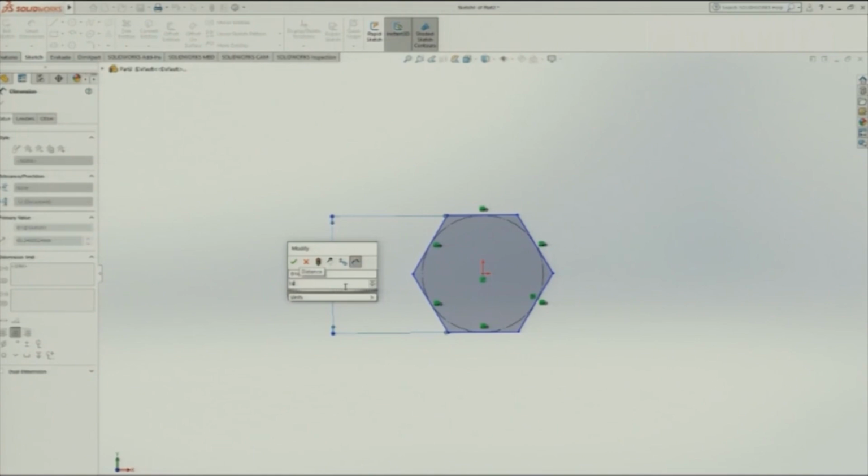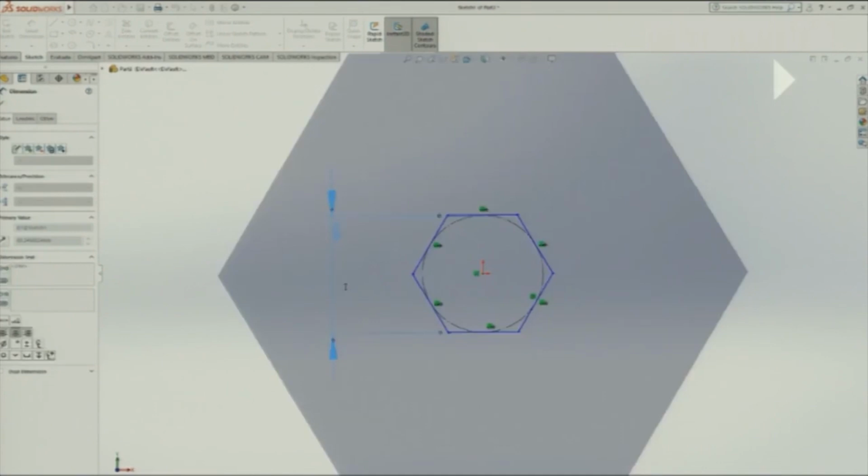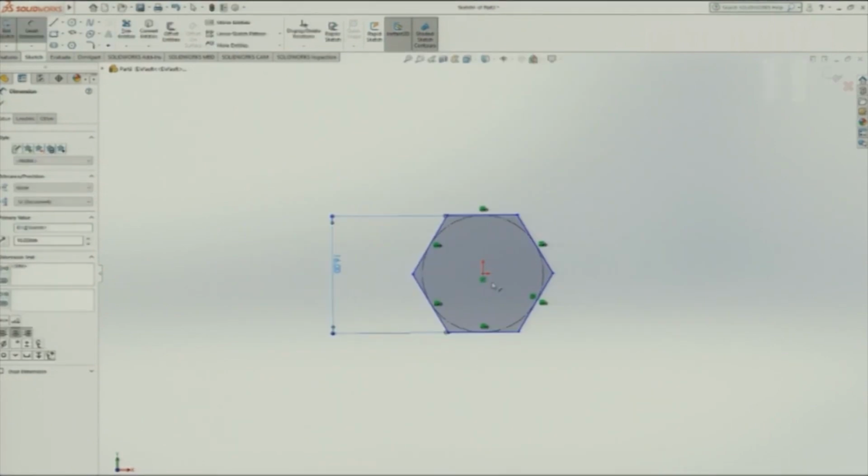My d here is 8 mm, as an 8 mm hole is there on the flange. I am going to put some value here, so that value 16 is selected. I am making a little change, I am selecting my own dimension. However, the width across corners has to be 2D, I am putting 2D for width across the edges. So, this is a customized bolt that I am making here, not a standard bolt.